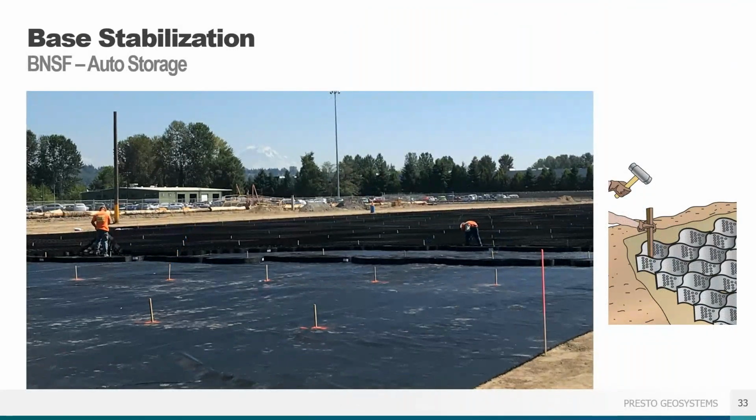Another technique tip important for large projects is to prep the site layout. In this case, the contractor wanted square panels for the entire installation, so they surveyed and staked the corners of each GEOWEB panel over the 25-acre site. Once the GEOWEB panels were filled, they just pulled the stakes.